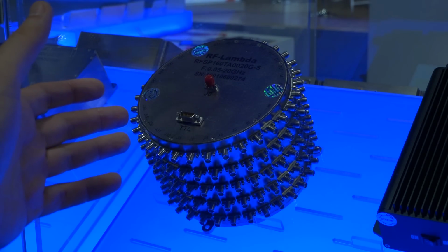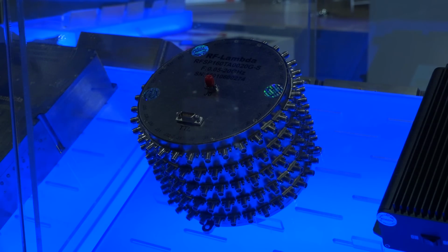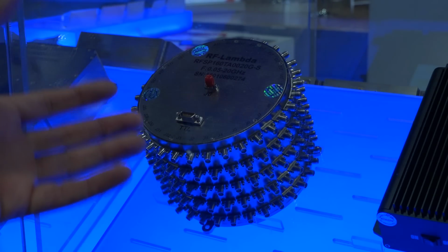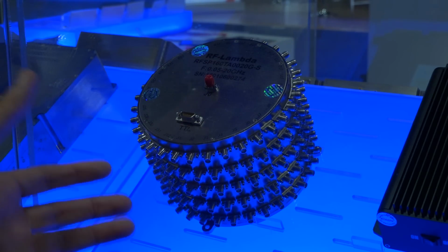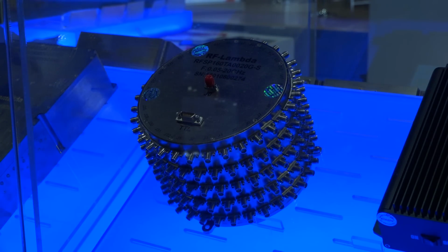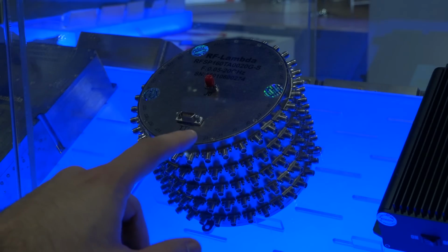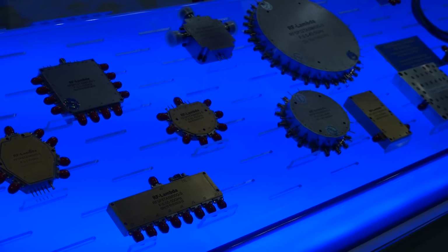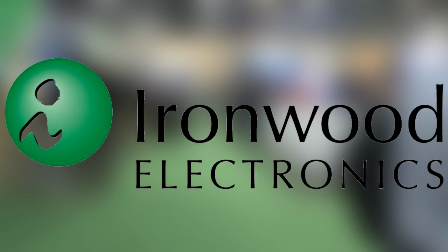This one goes from 0.05 to 20 gigahertz. And given the number of ports and the way it is organized, you could imagine phased arrays or antenna switching or any kind of places in automated testing where you want to deploy that. There are not that many switches this broadband with this many ports. I don't think I've ever seen one this complicated, but they also have a whole bunch of other switches, the electromechanical as well as solid state ones, for a wide range of frequencies and different configurations depending on the customer needs.